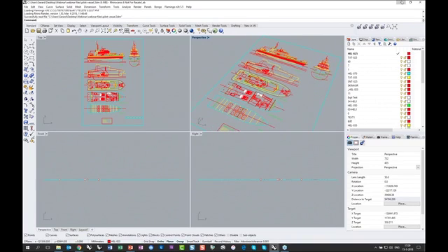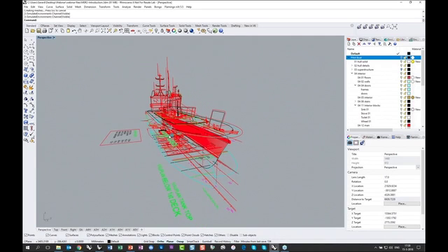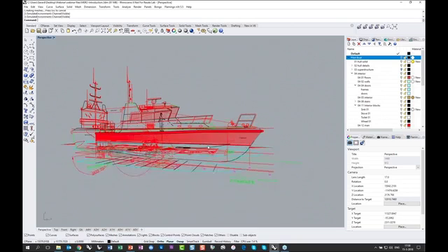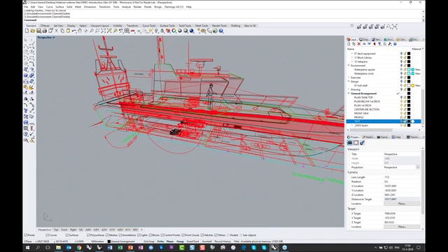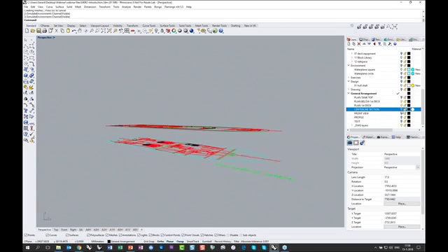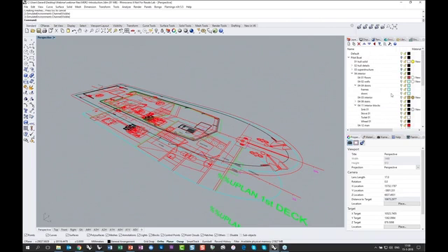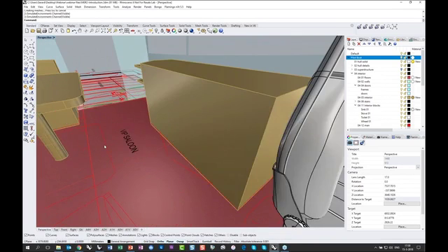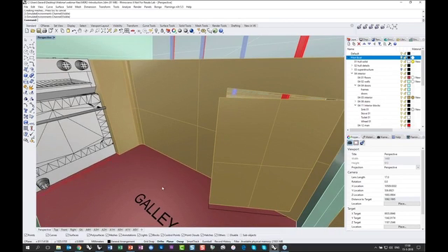And then the next file, and that's not this one, shows you how you can convert it, and then every deck is at the correct elevation. So I can simply turn off a couple of layers, and for example, the text of this drawing I can turn off, the profile part, the front view and the centerline section, and now I only have 2 decks that are at the proper elevation. And then when I turn on my pilot boat, you see that I can easily use this 2D information to create 3D geometry from it. And also on the deck below, here you find the footprint of this geometry.